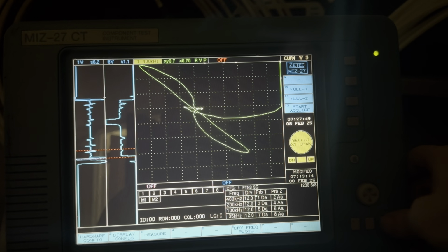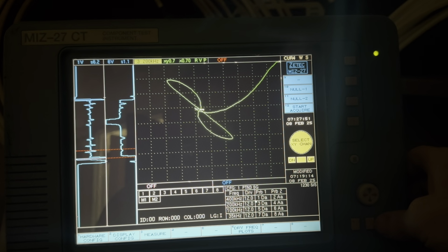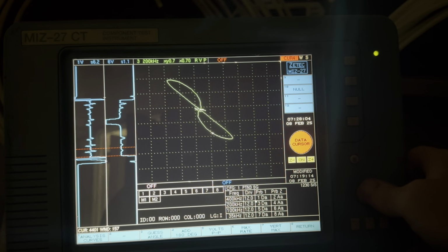I'm going to go to channel 3 next. You can see that I've set that one roughly the same. But when I measure, I've got to find the button in the dark here. And when I scroll up to the 60% flat bottom hole, wow, that's less than 90 degrees. On channel 1, which was a higher frequency, that signal was about 110 degrees. So there's less phase lag for the deeper flaw. Why is that? Well, because lower frequencies penetrate through the material quicker.